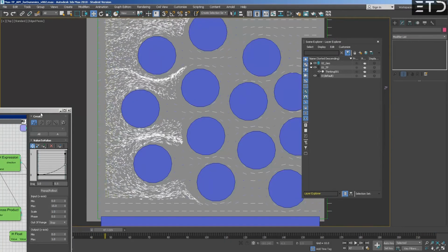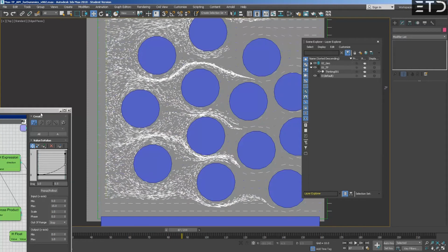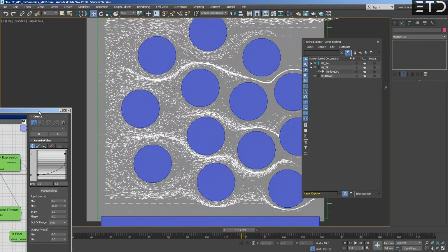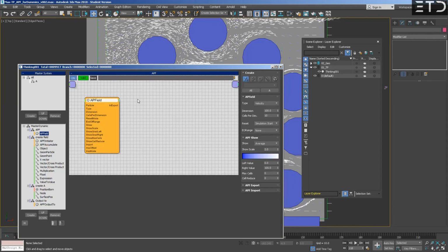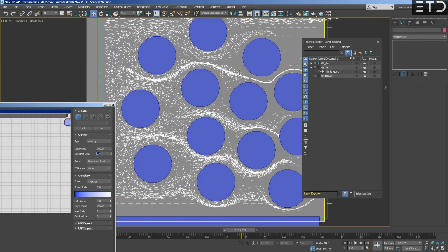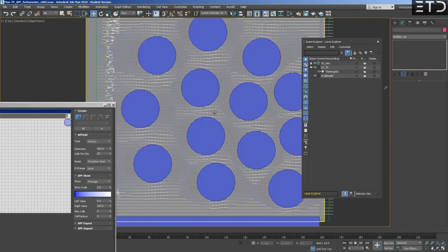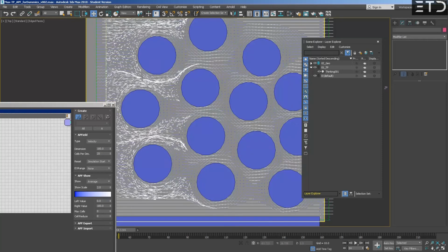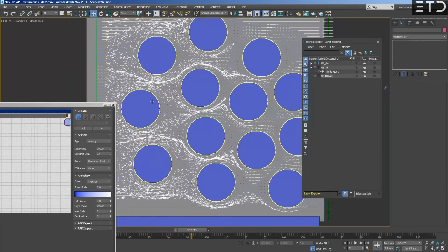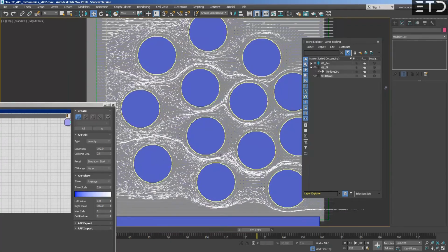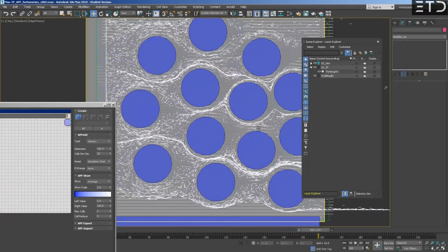It can also be the definition of this field, how it applies the forces. Yeah, we can try to increase the resolution. So if instead of 10 we go to 20 or 25 to see more effect, we will have many more points evaluated, so we should have way more definition now. We don't need to have a lot of definition, that's a cool thing about fields. It will interpolate between. Now we can see the effect. Now it works properly. Yes, it was that we didn't have enough resolution. That is pretty sweet.